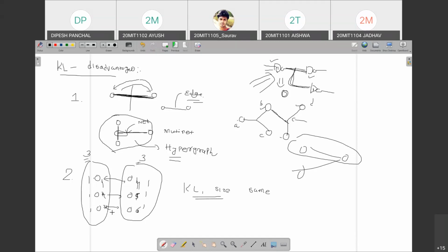But if the size of each and every gate is different, some gate is a NAND gate, some gates are OR gates, and then if you do the swapping, this balance criteria is not maintained. So it results in an unbalanced output.